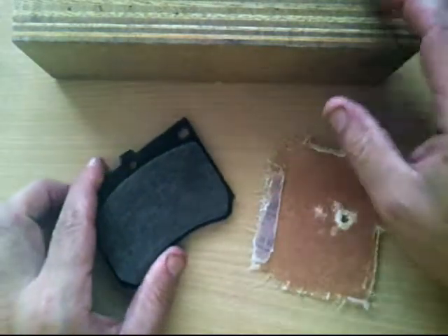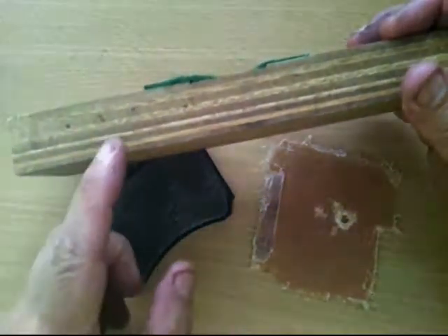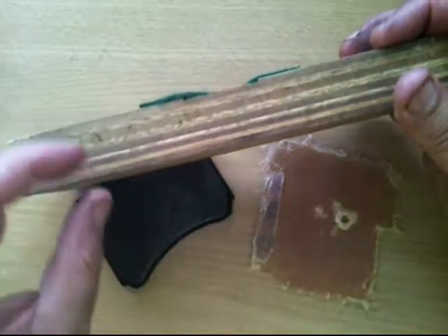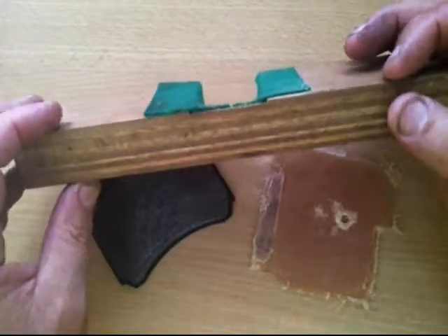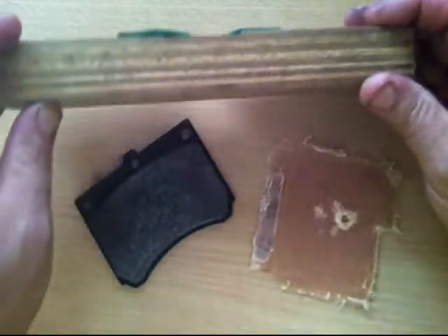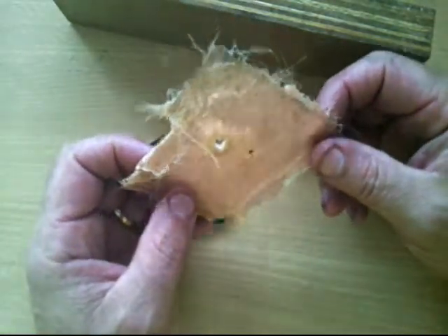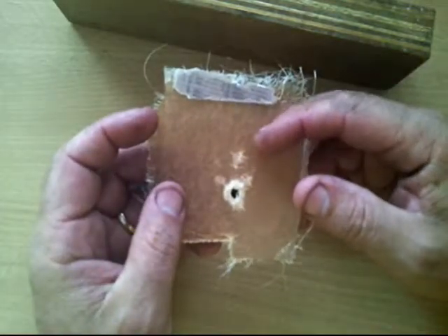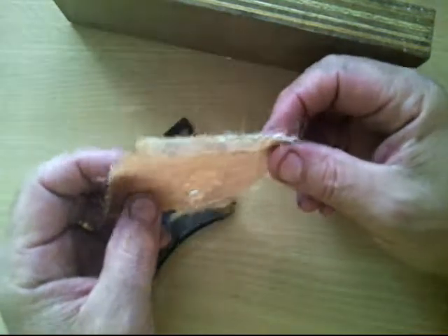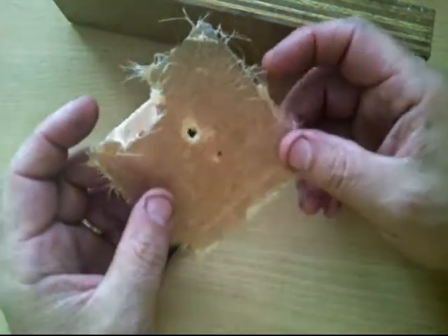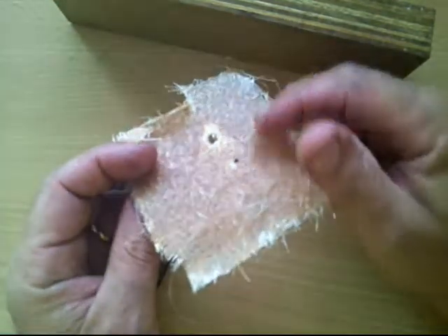The other thing that some composites can be is laminar. So here's a bit of plywood, and we'll talk more about this later on, but you can see there's sort of laminations where sheets of plywood are put together face to face, not edge to edge, to provide strength properties which the original timber doesn't have. And they can also be fibrous, and this is a little bit of fiberglass over here. It has a resin matrix, or a resin soup if you like, and glass fibres are embedded into that soup, changing the properties of the material, so it's quite stiff and hard, and you can see the fibres there.